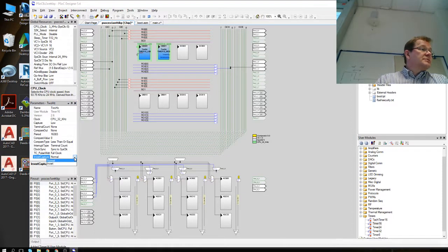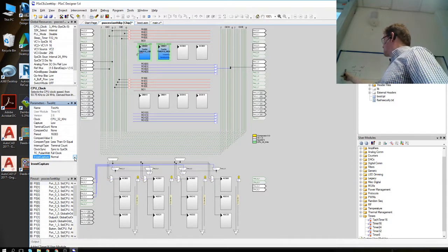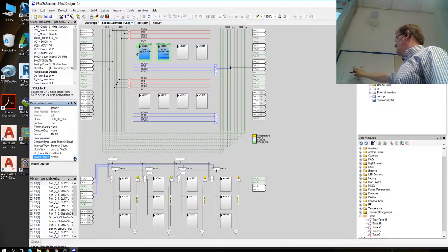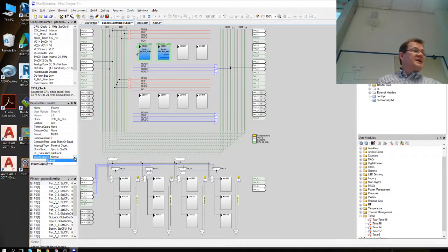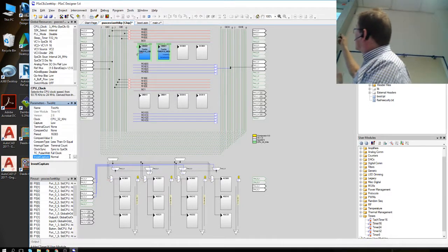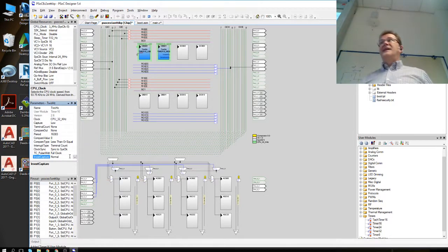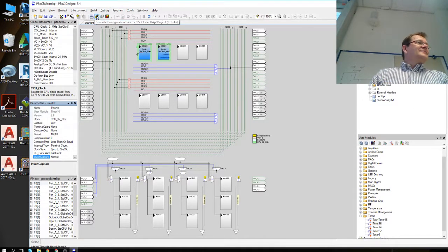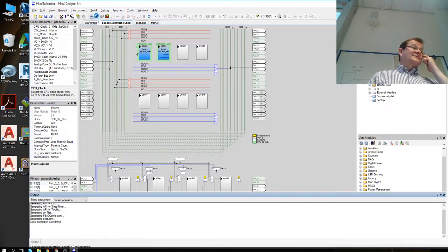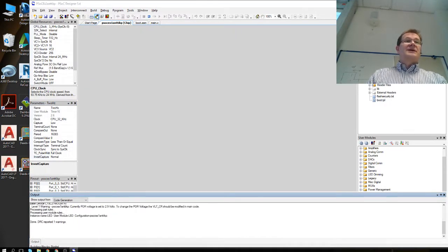Invert capture. Okay, so meaning PWM, which side is it? This way or inverted? Good. So in principle, now we have the timer set up. We just need some code. Let me generate the header file to see what kind of code we actually get there.